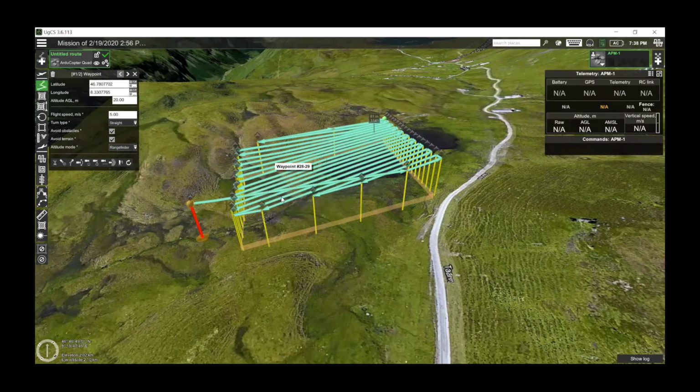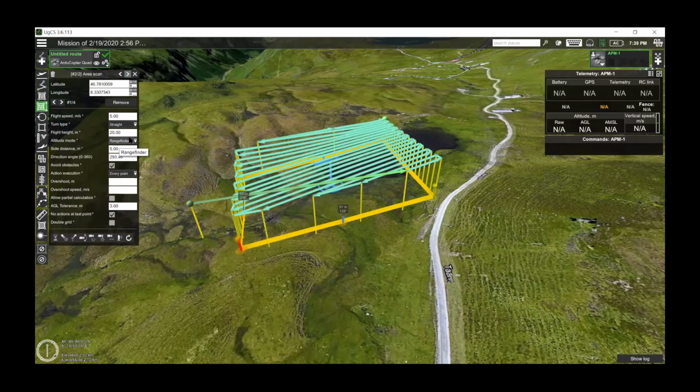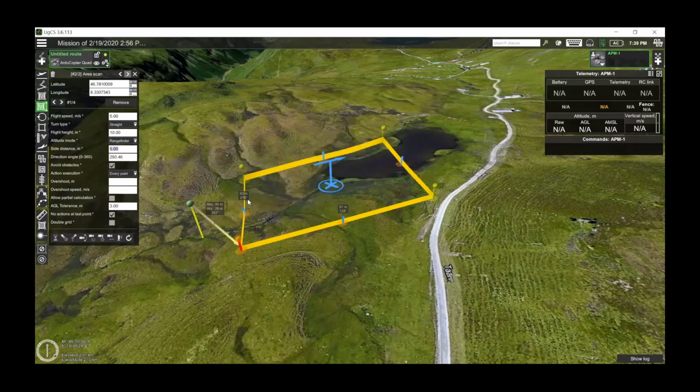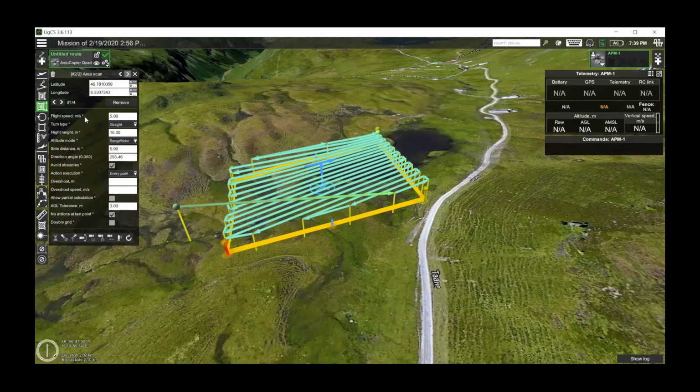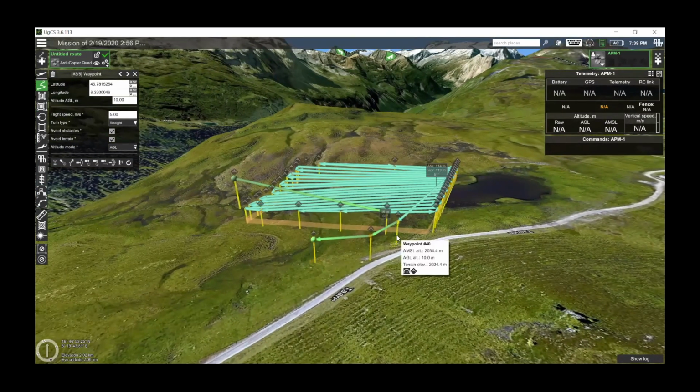It can be used for the whole route. It can also be that at the beginning you fly, for example, AGL, and from the next segment or next waypoint, you can change the altitude type to rangefinder, specify the necessary flight altitude, creating next waypoints or using some next tool. It is possible also to keep the same altitude mode or change to AGL. The only rule is that the turn type must be straight to use the rangefinder.